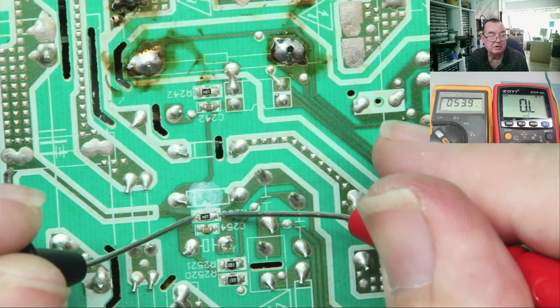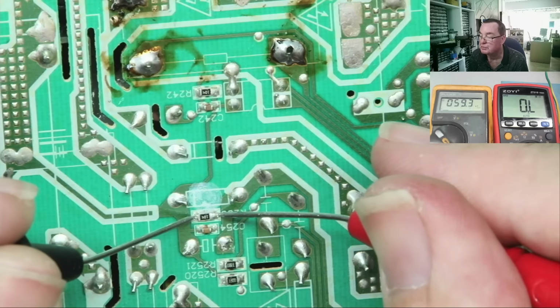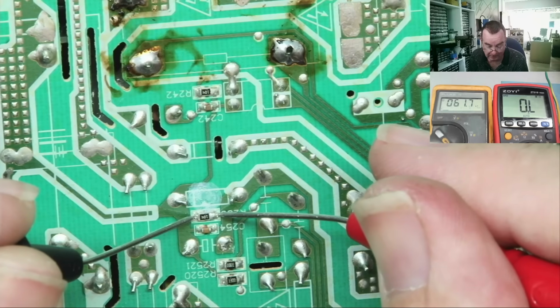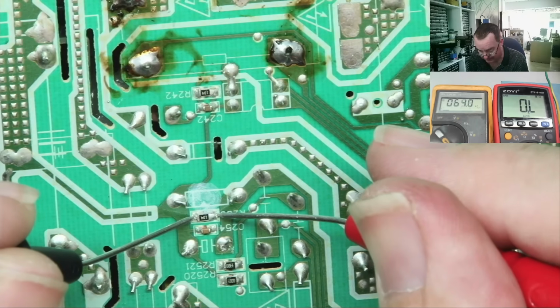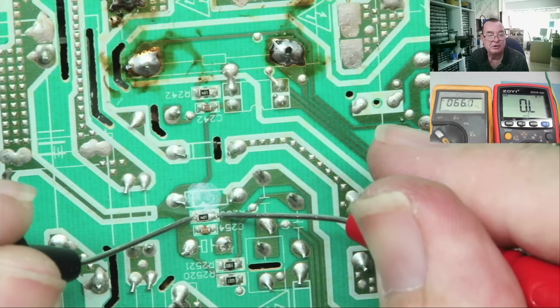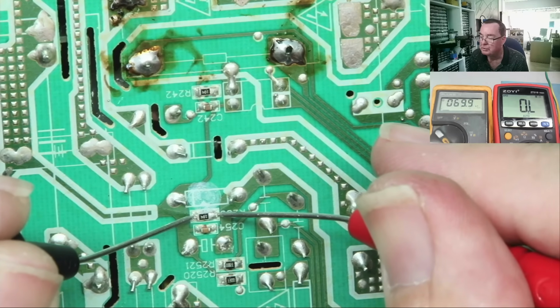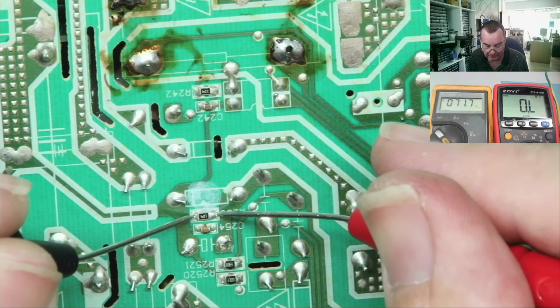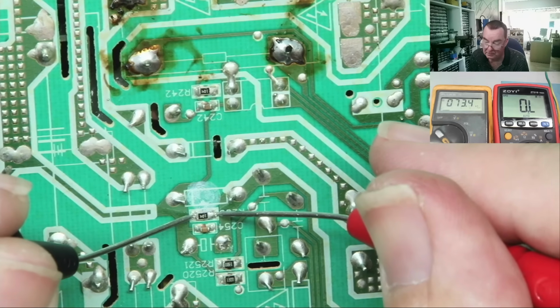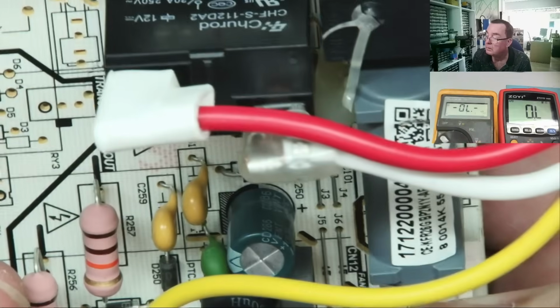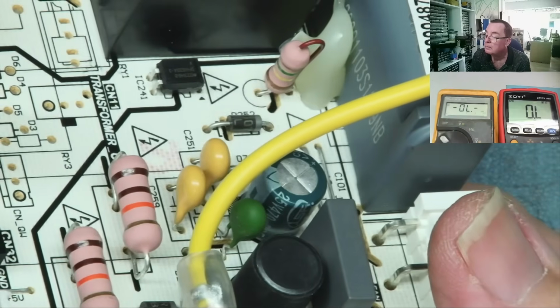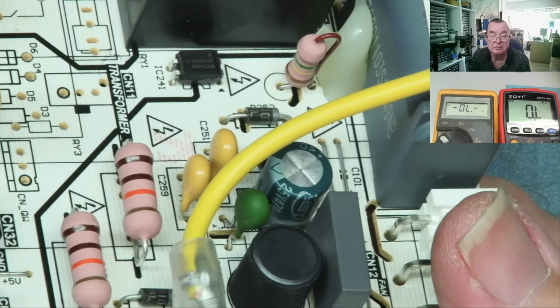It may be lower because the capacitor probably has some leakage current, which will show as resistance, and also it goes to something else in the circuit. But you see, it's not going above 100 now. So don't let that catch you out when you have auto ranging on ohms range and you're poking around boards and you've got resistors wired across capacitors. Now it looks fine. This capacitor is this one here. What are you? 470 microfarad, 25 volt.